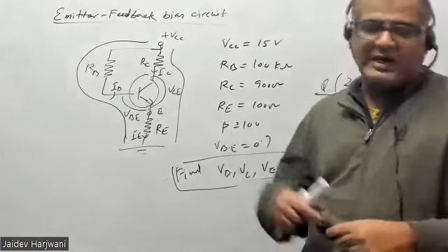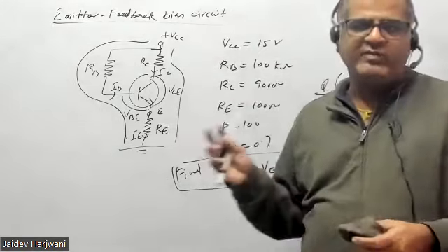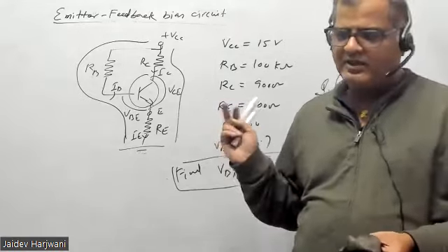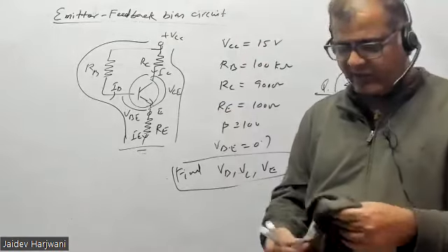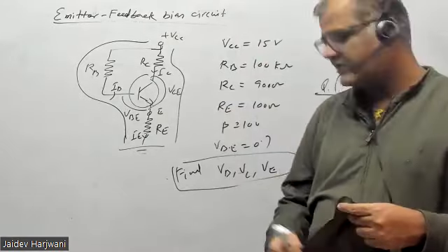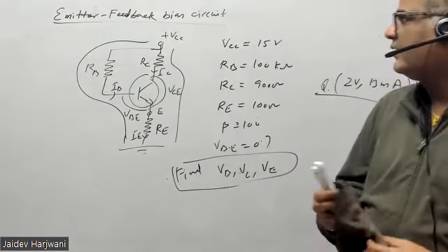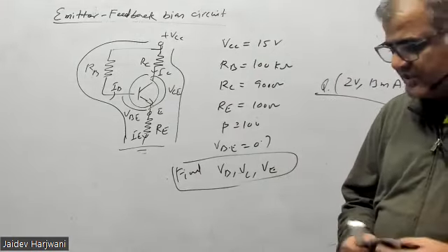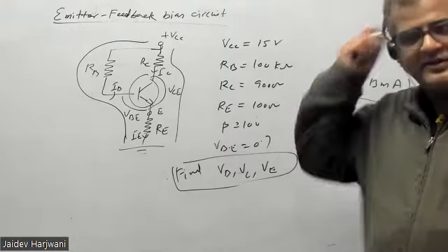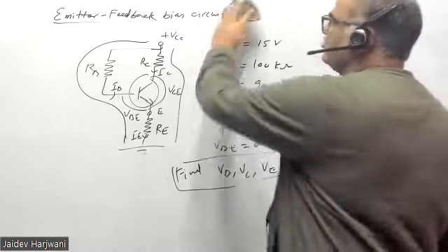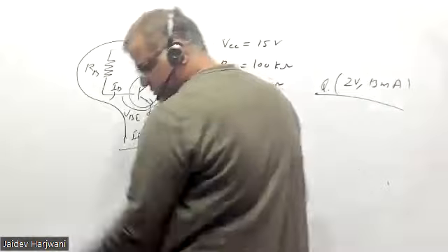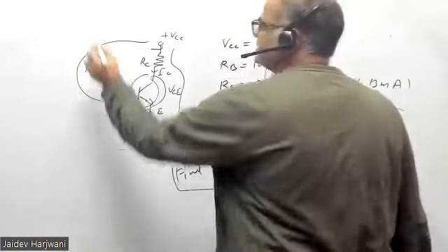So now I am going to do the circuit which is independent of beta, which is commercially used. These circuits are just for calculations. The commercial circuit we use for biasing is the voltage divider bias, which is independent of beta. It is most important for the exam also.